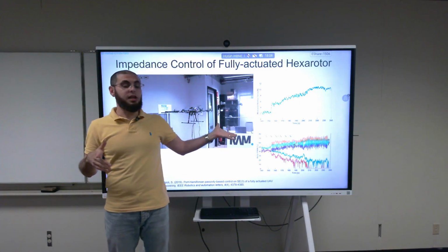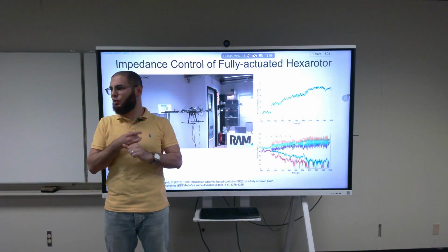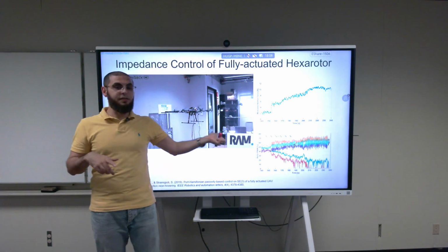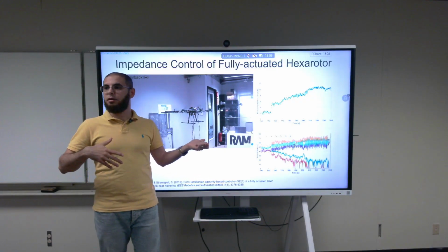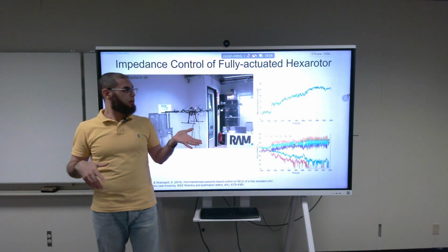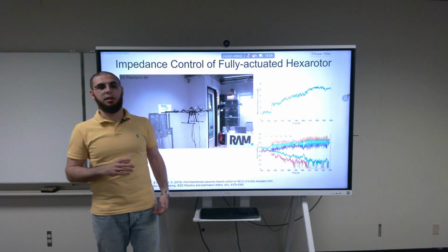This is not the impedance controller where we cancel things out. This is just the impedance controller where we have gravity compensation and the spring and the damper. So this is a very, very robust controller because we're not taking the dynamics and killing it. We're just keeping it as is, and we're just modifying the impedance in this way. And you can actually show this, it's much better performance-wise, and this is just the proof.